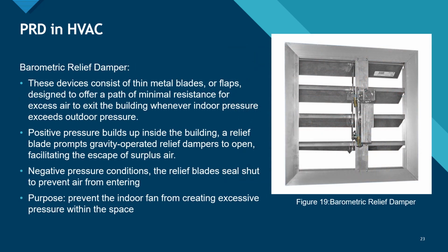One unique application of PRDs and HVAC is the barometric relief damper. These devices consist of thin metal blades or flaps designed to offer a path of minimal resistance for excess air to exit the building whenever indoor pressure exceeds outdoor pressure.